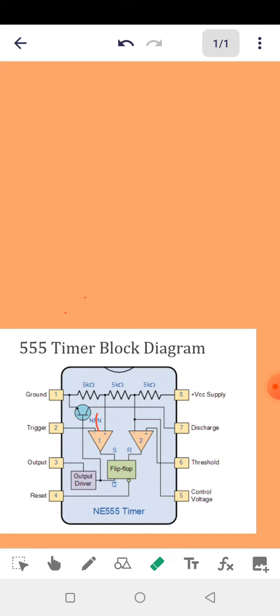Now the threshold voltage, pin 6, works with 2/3 of VCC. So when we have a voltage that is greater than 2/3 of VCC, the threshold pin will be activated. Threshold, you know what threshold is, like when you get to a limit. We use that feature many times with timing. So let's say with timing, when the voltage charges up to a little above 2/3 of VCC, then I think the discharge will just set in, for the operation of your application to work the way you have addressed it.